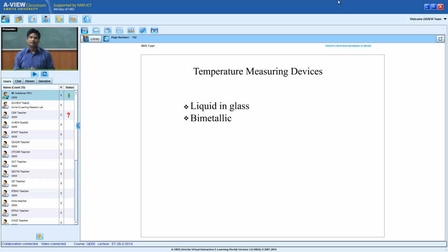I should know the temperature at which cotton burns and the temperature at which polyester burns. So that's how the designer will give you small cutoffs. Whenever I'm ironing polyester, I set it to polyester and automatically there is a connection which changes its length. Those are called bimetallic strips. Without proper temperature measurement and control, you can't have an ordinary iron box.